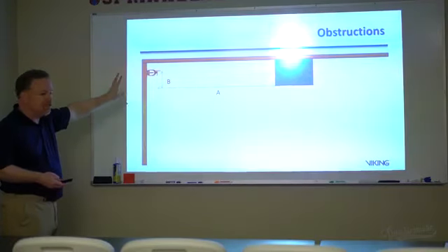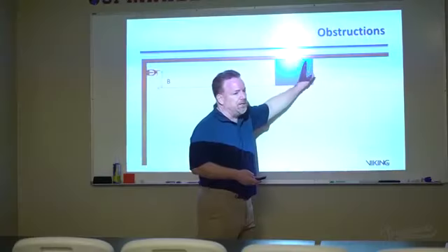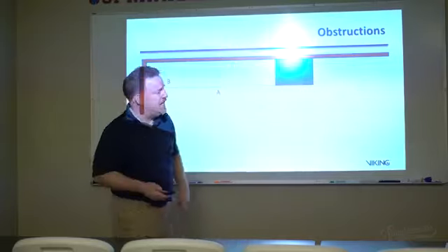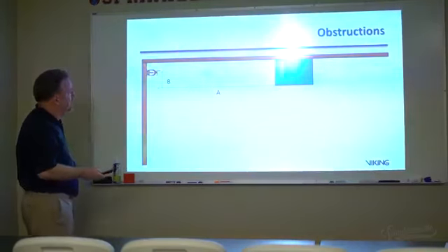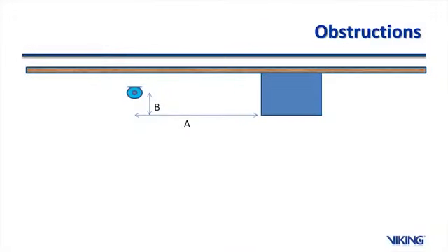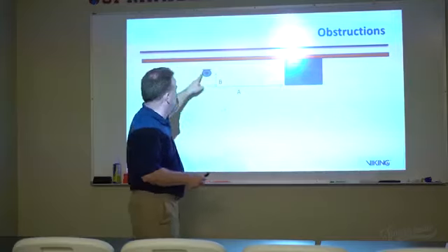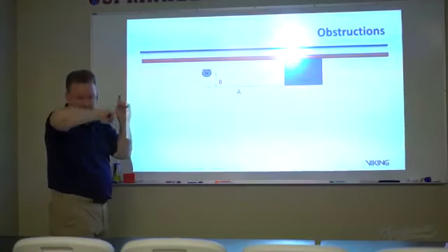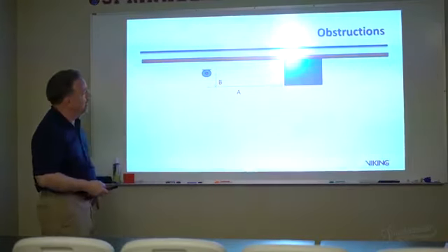The beam rule has a slightly different application, because the obstruction could exist not only out in front of that spray pattern as I'm coming out into the room, but also as 2 beams coming out along the side, because that spray pattern develops along the side. So the beam rule is applied both in front, in the spray pattern that goes out, as well as the spray pattern that goes down the wall.